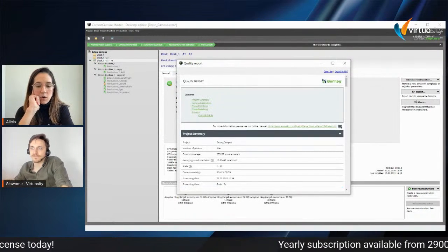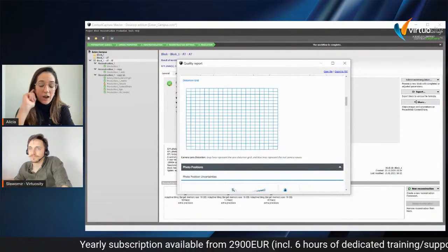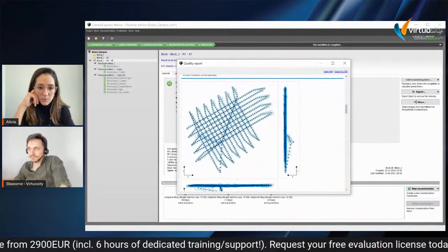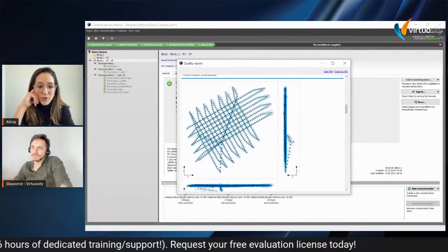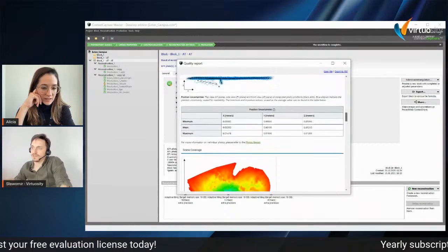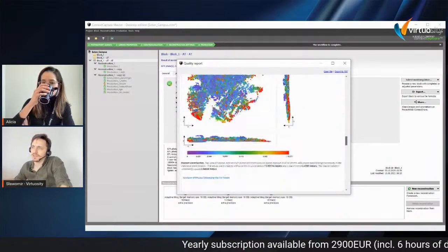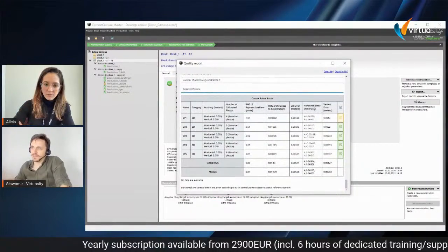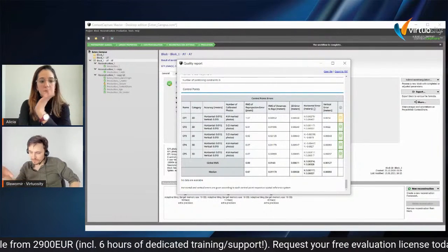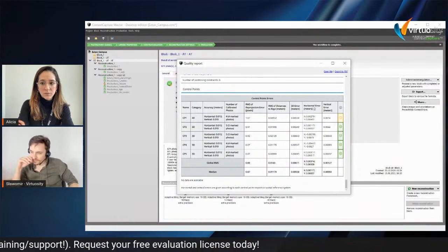Mike didn't use QR codes for the control points, but just to share with you, and I think it's also covered in the video we created for these projects, you can print QR codes and then the control points will be automatically identified in the pictures. Is that right? Exactly. This is one of our ways to automate the process. You can print and generate as many ground control points as you want, which will be created as AprilTags for aerial photogrammetry.